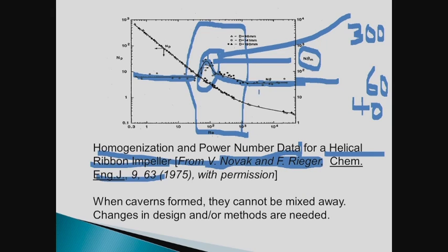The other thing you should recognize is maybe you start turbulent and you wind up laminar. So it could be that you're going to pass through the transition regime. You're mixing very well until you hit the transition regime and you mix poorly, and then you come out of the transition regime as you're getting thicker and you're mixing better. So that's an idea here.